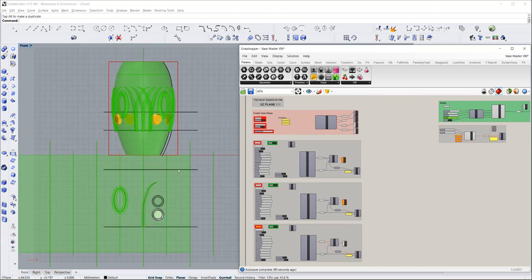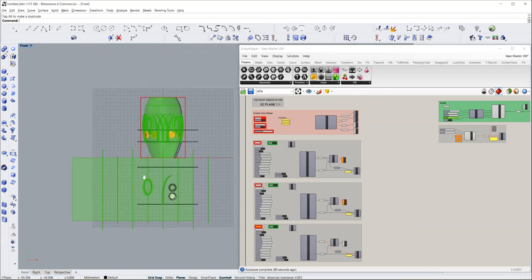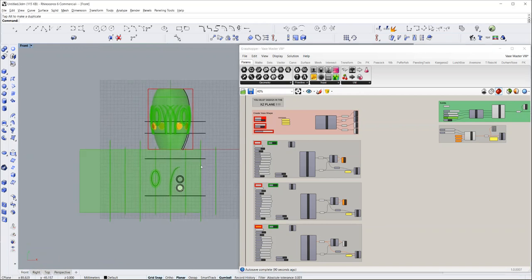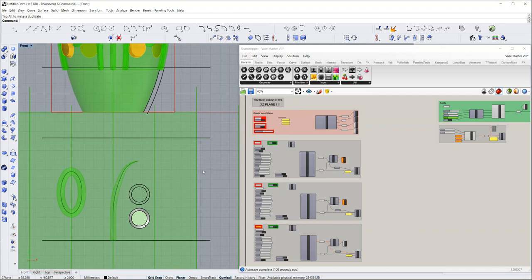Some cautions: trying to work right on the edges of these is dangerous, on these vertical edges. If you do by accident, and it can happen, I've done it several times, you get too close and you're at an angle, and so the shape starts to go outside that, your regeneration time gets really long because it's working out in outer space somewhere. I've had it stall my system for as long as 11 minutes.